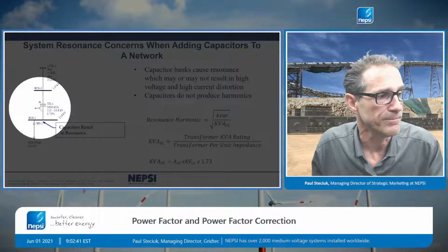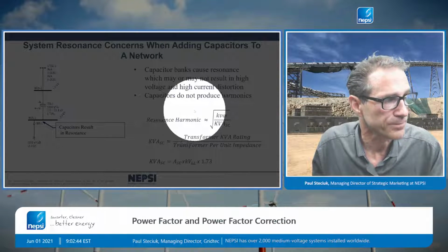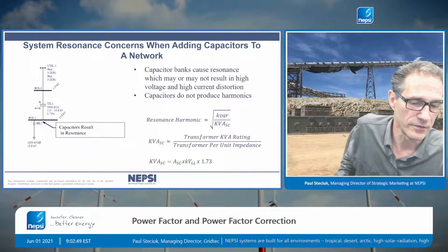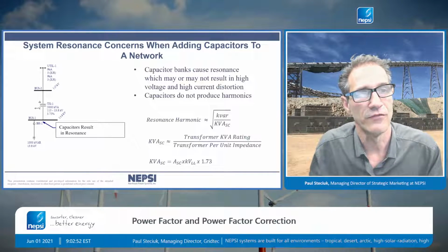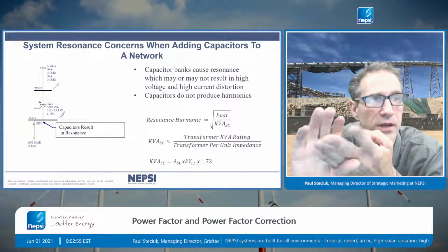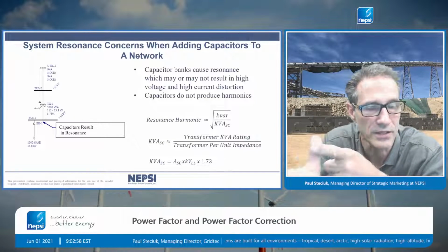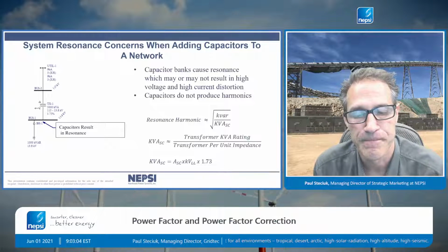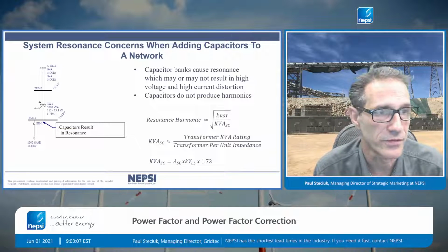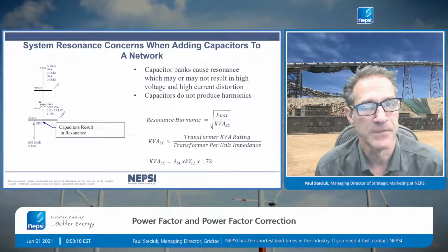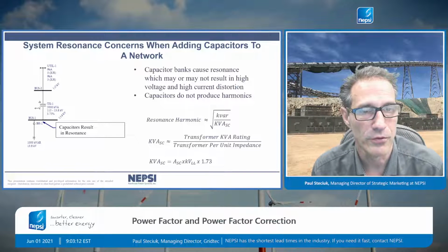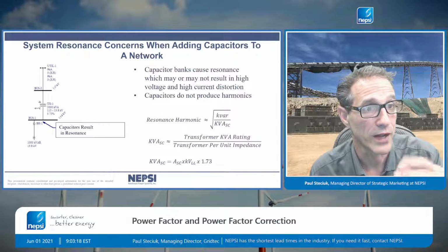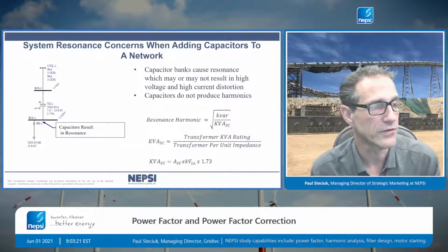Just remember, in this case, if I have resonance near a value of harmonic current that exists in the system, VFD drives produce 5th harmonic, 7th harmonic, 11th, 13th, 17th, 19th, and so on. This is also true for rectifiers: 5th, 7th, 11th, 13th, 17th, 19th harmonic. And if you have high pulse devices, you may have a 12 pulse device. Theoretically, it will not produce a 5th and 7th harmonic, but in reality it does. It produces low levels of 5th and 7th.